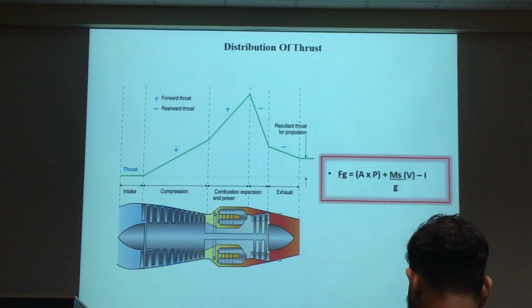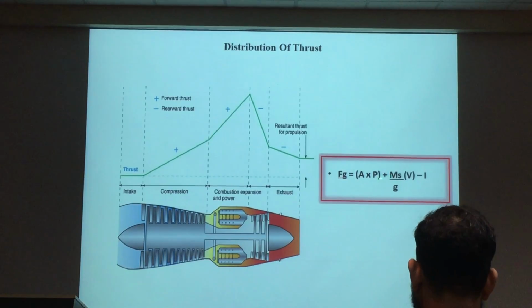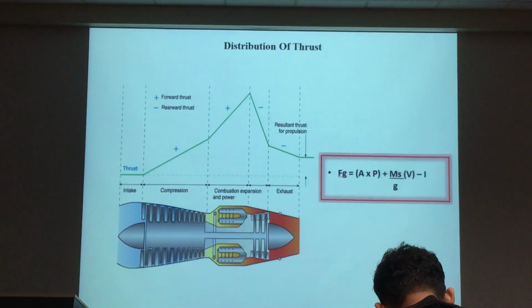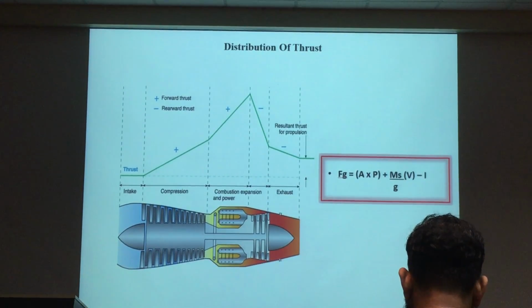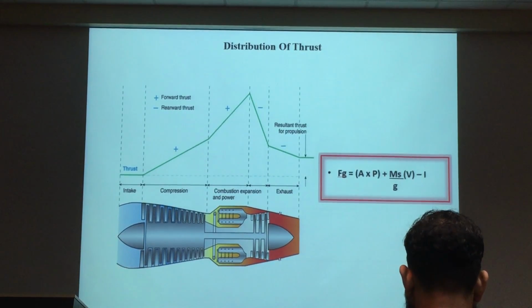Okay, now you compare the other formula to this formula. Area temperature. Okay, we will refer to this pressure change. If they give you static, you have to minus off the atmospheric pressure. Atmospheric pressure, usually as static at mean sea level, is 14.7 psi. But normally they will give you the pressure difference, not the static absolute value. Understand this? During your lab lesson, all your stages, the pressure given there is a pressure difference already. You take atmospheric as 0.